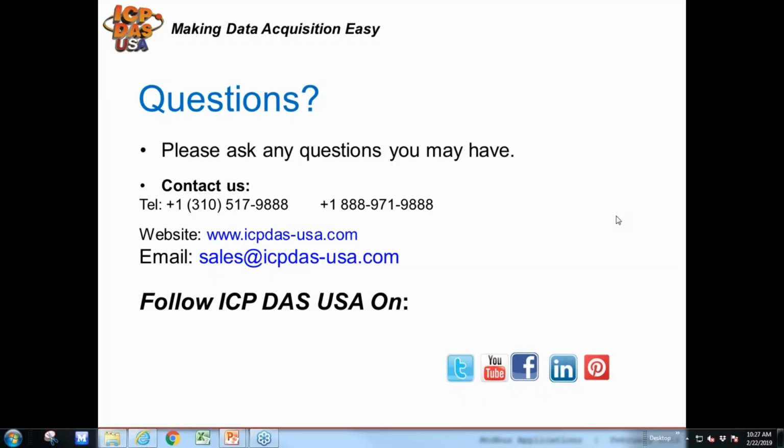But if you have multiple COM ports, in this case COM1 and COM2, I believe you're talking about our TGW modules like a 725. A device connected to the IP address and port 502 of COM1 would be a different bus than the IP address and port 503. So yes, you can have multiple devices with the same slave ID along each bus, because they're differentiated by the IP address and port number. If it was for a different module, please let me know and I'll revise the answer.